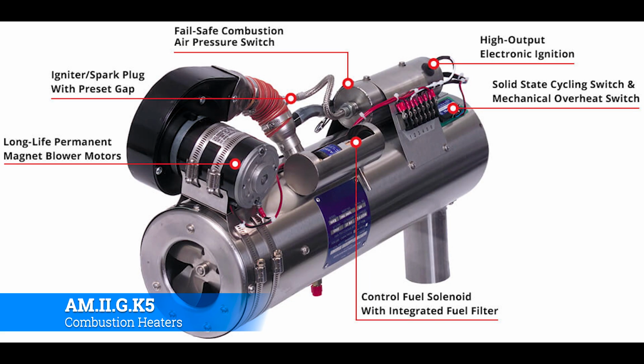Now, what does that mean, and what can we expect from combustion heaters? Aircraft combustion heaters are used in a lot of small and medium-sized aircraft, and they provide a heat source that's independent from the aircraft's engine, but it still uses fuel from the main fuel tank, so it can be kind of confusing. It's using combustion, but it's generating its own combustion, not using the combustion that's happening right in front of it. The source of the heat in this case is an independent combustion chamber and is located